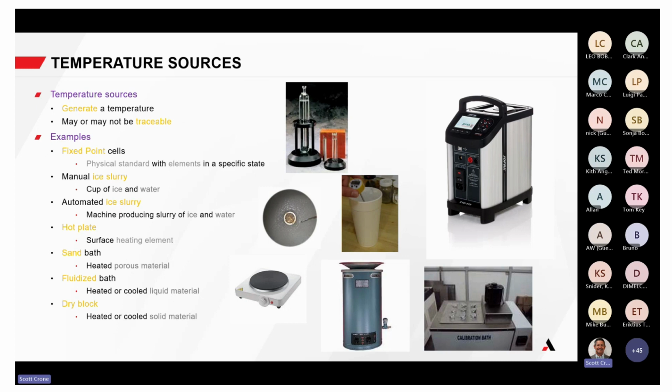People do that, and they'll boil water, and they'll drop a thermometer in there and say, well, it's got to be 100 degrees C, or it's got to be boiling. Well, that's great, except that you may not be at sea level. You may have impurities in the water. And it's only good right where you've got that 1 point of contact. It's also only good if you've got a traceable thermometer in there to reference it.